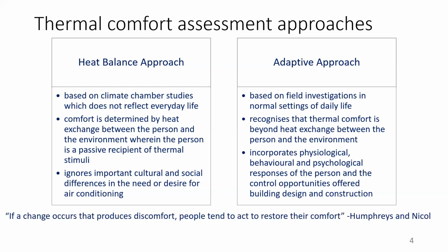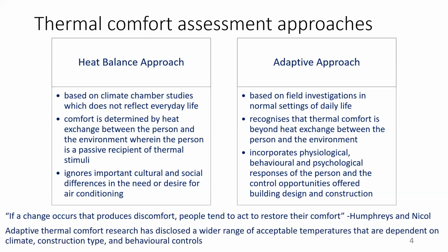This quotation that I have taken from a paper by Humphreys and Nicol summarizes the adaptive approach to thermal comfort. If a change occurs that produces discomfort, people tend to act to restore their comfort. And today, adaptive thermal comfort research around the globe has revealed that a wider range of acceptable temperatures is possible, and that it depends on the climate, the building construction type, and behavioral controls as well.